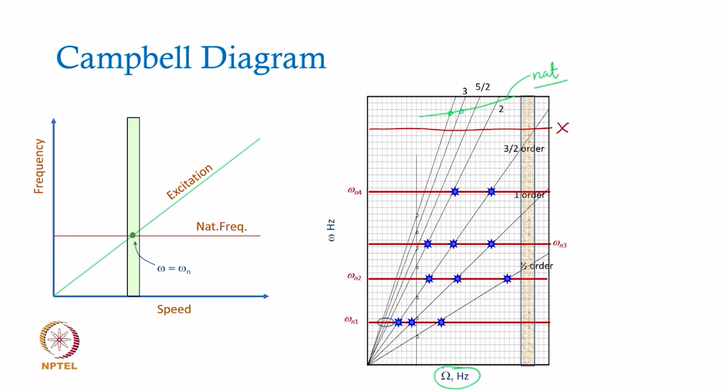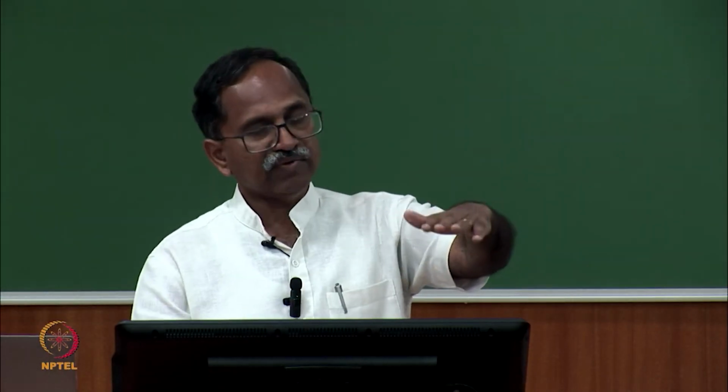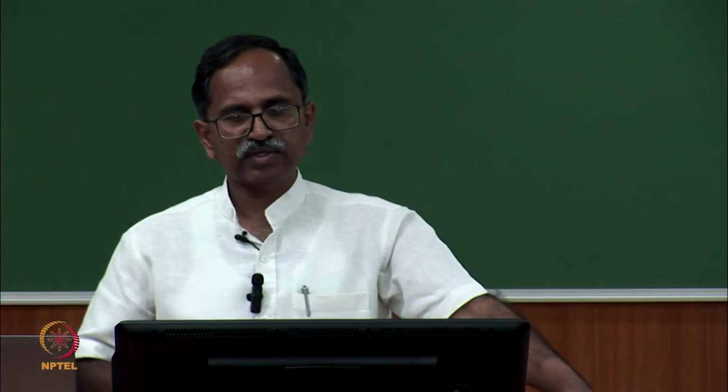When the blades rotate at very high speed, they basically get stiffened at higher speeds, and that will increase the effective stiffness and the natural frequency. Therefore, the natural frequency will curve upwards.